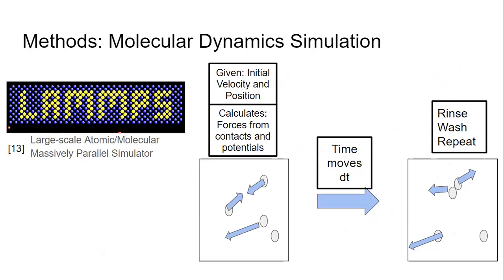the simulation. It then calculates any sort of contact force or long-range potential on those particles and takes some time step forward, where it then moves the particles, and at the next time step, again calculates the forces of any kind, and moves the particles again through another time step. Each time step there's assumed to be constant forces, and it just does this over and over again until you've been able to simulate some sort of physical event.